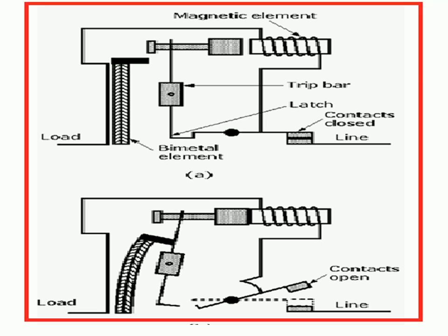And the second method: under the normal working condition, the slug is held in position by a light spring. This operation is due to the magnetic field. The magnetic field developed due to the flow of current is not sufficient to attract the latch. This happens during normal condition.